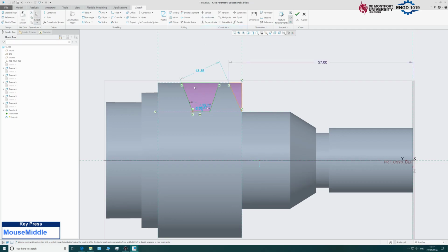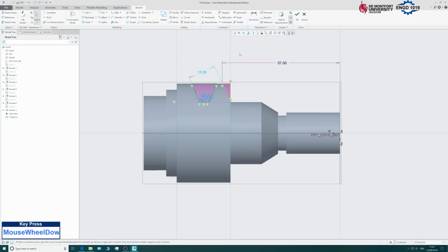So use the line tool and just draw a basic representation of the geometry. Okay, so it's obviously tried to dimension this up, but it's not made a very good job of it, so let's add our own. So dimension, so again, baseline, left click, and hold Control, left click, let go of Control, middle mouse button. So on the drawing, this point here is 61. Okay, so I'm going to add dimensions to each one of these points.